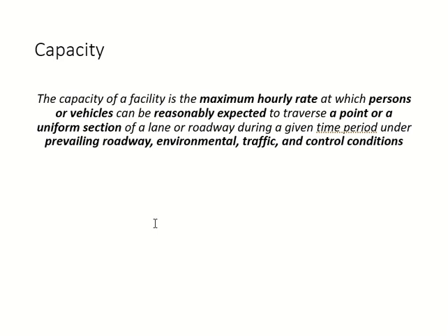And then we have the control conditions. Control conditions mean anything which you are doing on the road to control or manage traffic. So for example, lane markings, speed humps, speed cameras, roundabouts, signals. So obviously, if I remove a signal from an intersection and build a bridge, so I played with what? I played with the control condition. So now the capacity obviously will change.